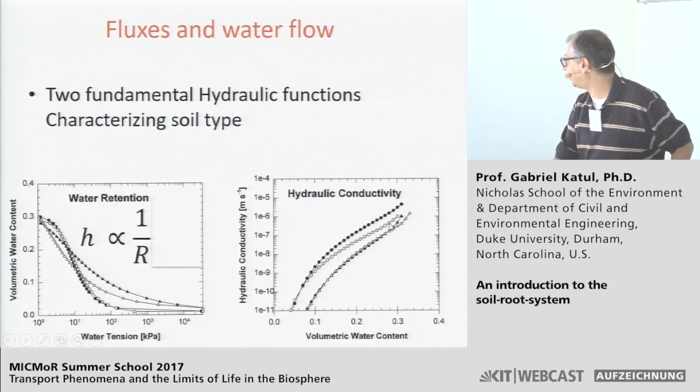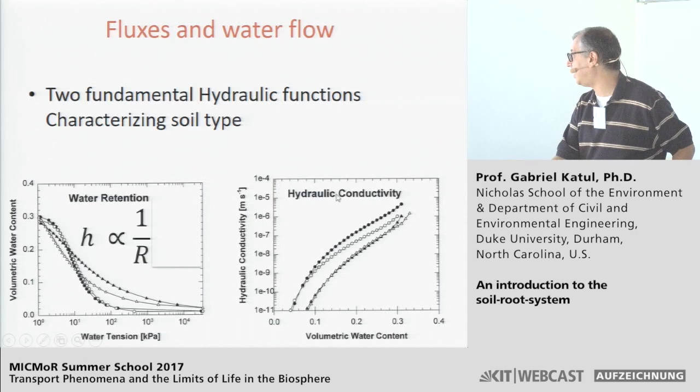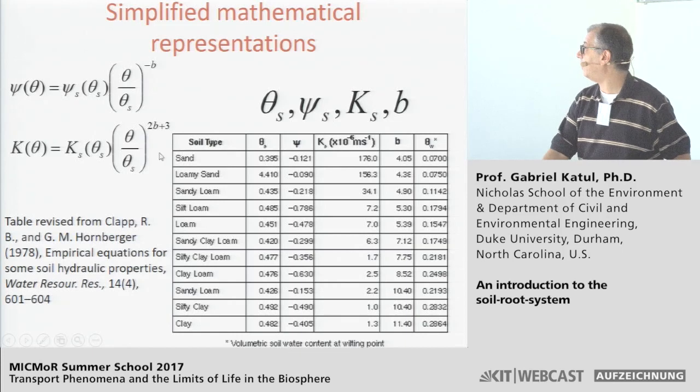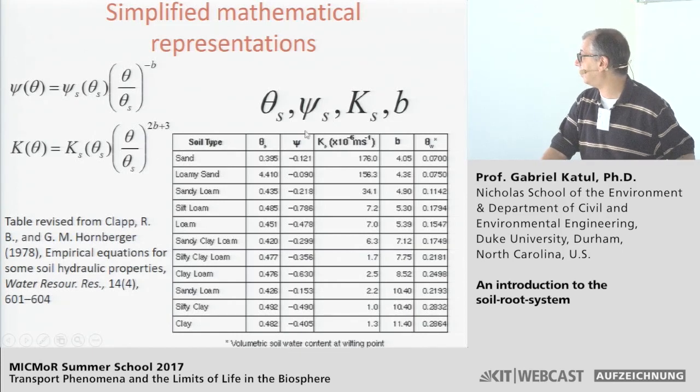So of course, now what we could do is, there is some connection between the particle size distribution, the pore size distribution, and the curvatures of these functions. What is done in practice is to try to put it all together through some empirical relations. And those have been studied extensively in the literature.